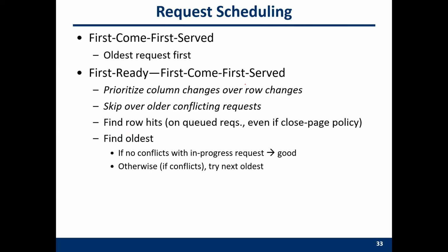Sometimes the memory controller will also give higher priority to the request that will have a row buffer hit. Now in one bank, one row has been opened. For example, this is my row buffer and this is my row. This row has been read into the row buffer.